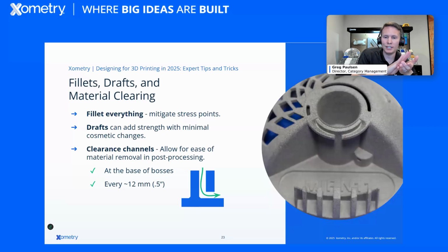If you add a little exit hole right at that base, it's going to give a channel to let air flow and clean out those hole areas. So it's really great when you think about designing for additive to add those exit holes. And because we have that freeform design, it's not a bother to the part design as well.